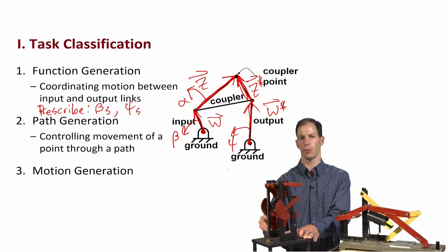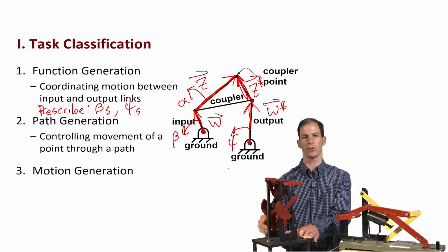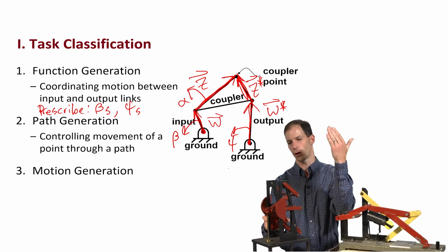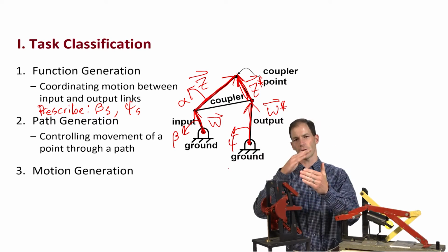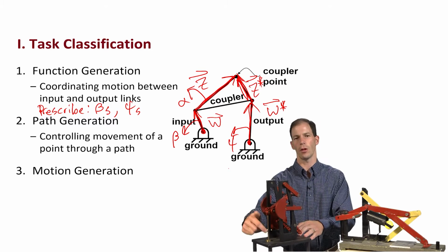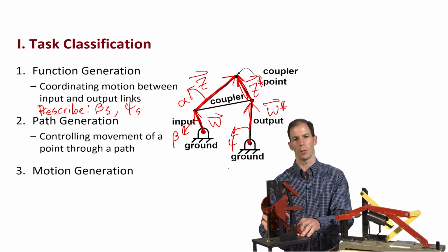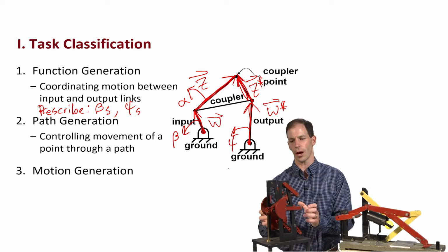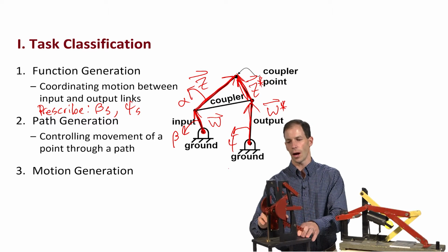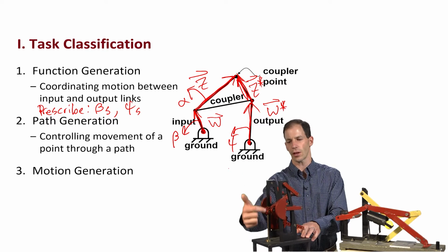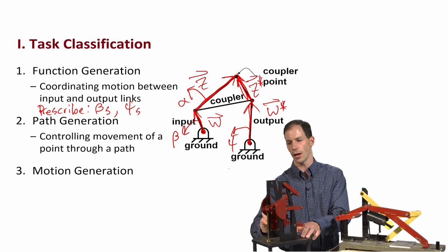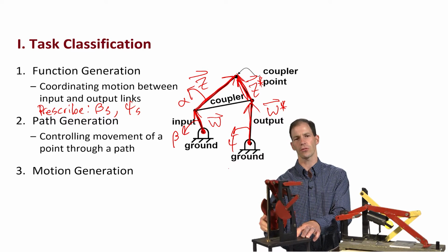Now, if you head out to western North Dakota or Texas, you'll see lots of what they call horsehead type oil pumps, moving a large piece back and forth with an arced head, moving a cable up and down, or sometimes a rigid link up and down in the ground. Well, those are quite bulky. This is a more compact design of that same thing, where I'm able to create very close to a straight line motion, which is needed because I'm moving right above this vertical well. And as I rotate this, you'll see I move almost in a straight line up and down above that